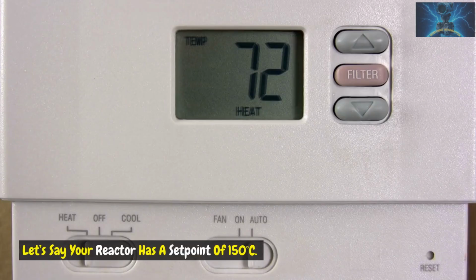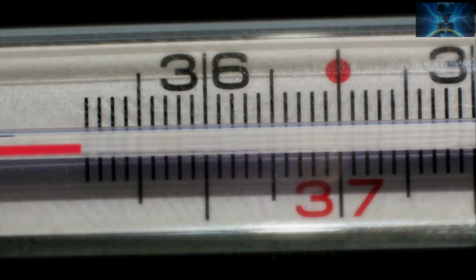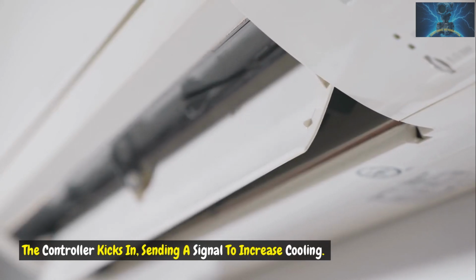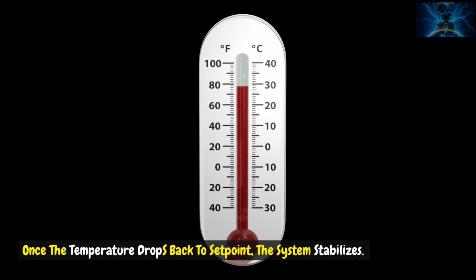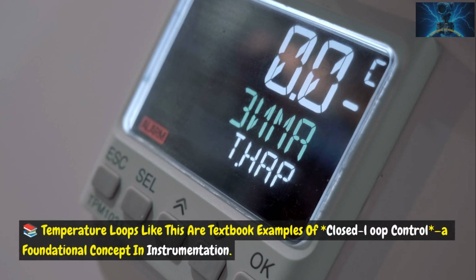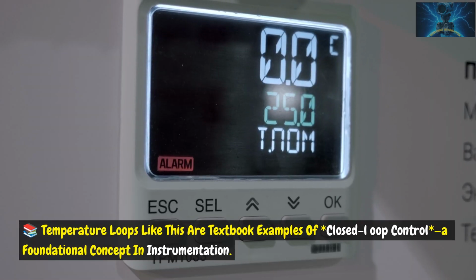Example: let's say your reactor has a set point of 150 degrees C. A thermocouple senses that the process is drifting up to 153 degrees. The controller kicks in, sending a signal to increase cooling. Once the temperature drops back to set point, the system stabilizes. All of this happens in real time, automatically. Temperature loops like this are textbook examples of closed-loop control, a foundational concept in instrumentation.